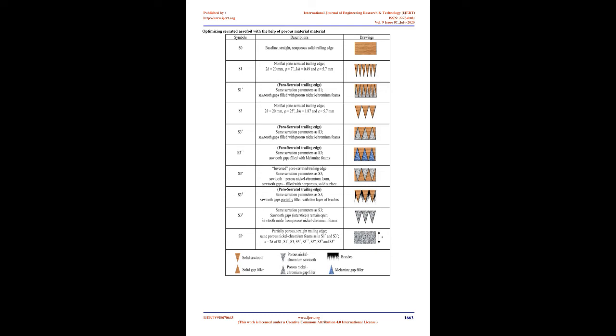3. NACA 6512-10. A steel body of 0.1 m length and detachable trailing edge. Cambered profile 0.16 m and 0.45 m span. Same as in the first. Same result. It also shows that noise reductions take place up to 7 dB over a wide frequency range, whereas the noise is increased by 3 dB at higher frequency.